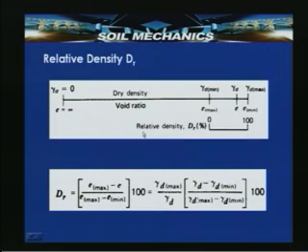So, if you look at this scale here, at e equal to infinity, the unit weight of the soil is 0, and at e equal to e minimum, the soil can have gamma d max, that is the maximum dry unit weight. At e max, the soil can have gamma d minimum, that is the minimum possible dry unit weight of a soil.